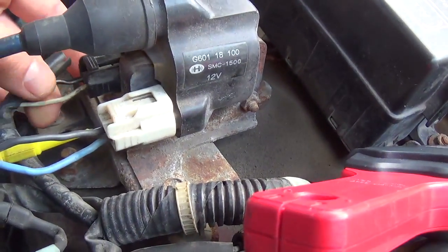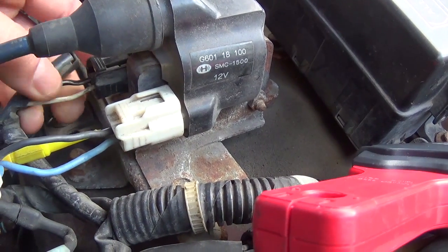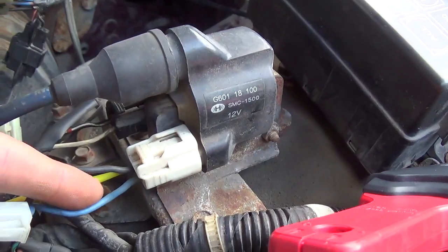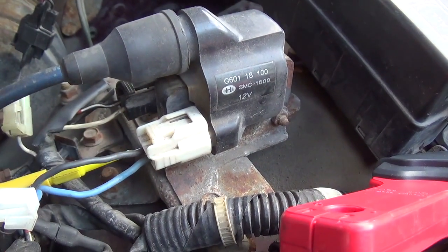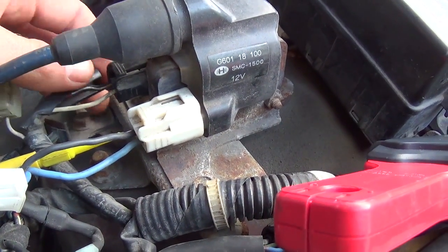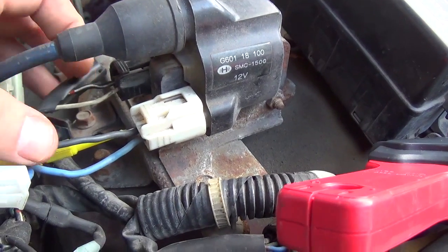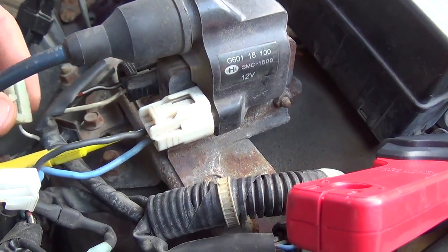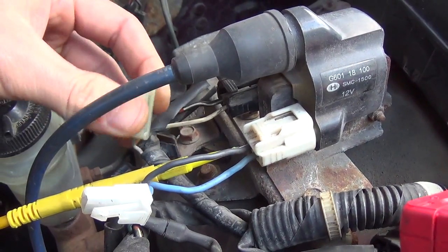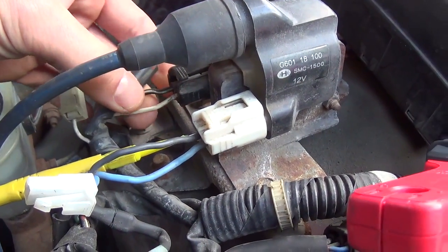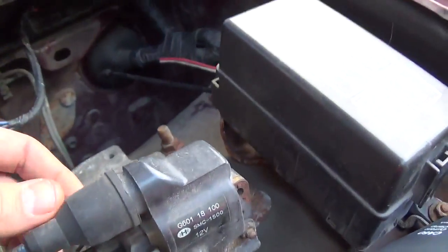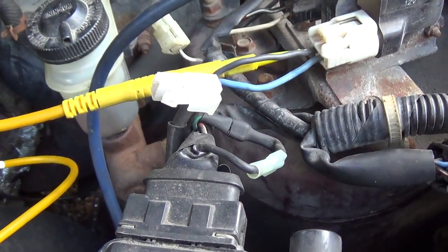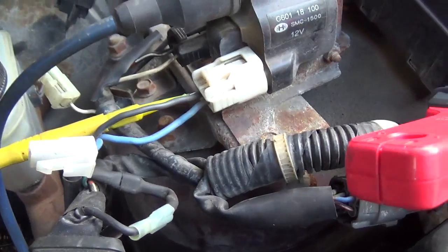The white wire next to it is attached to the control wire here, the blue. So you see 4 wires, but they're actually 2 separate circuits. So this goes to our computer and our tachometer, and there's actually a little test port here. So that's how our tach works. And then the second connector, that's the conduit that goes to our distributor.